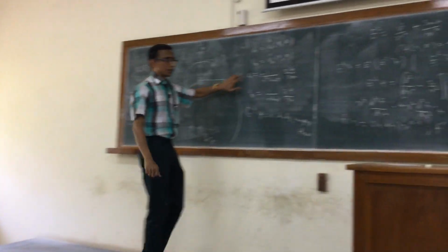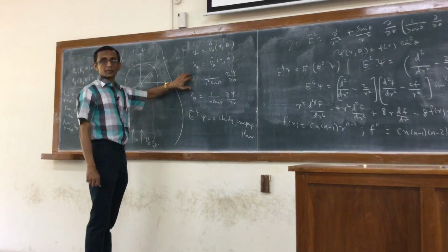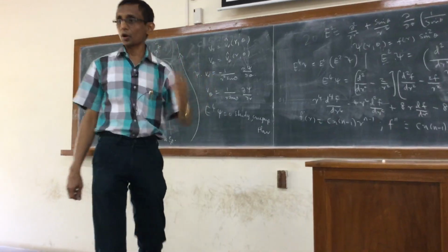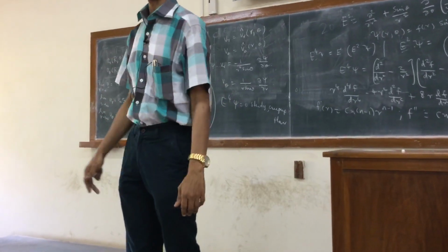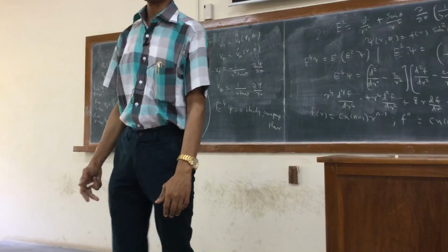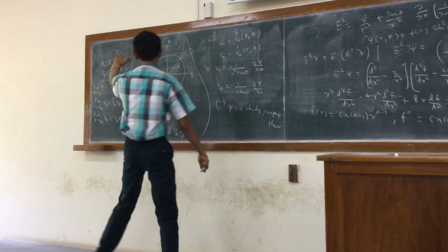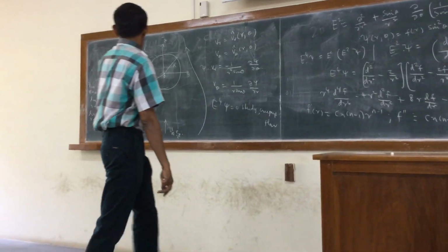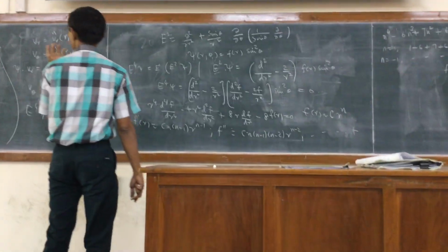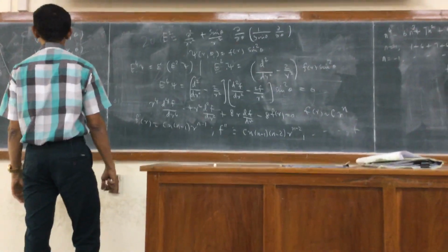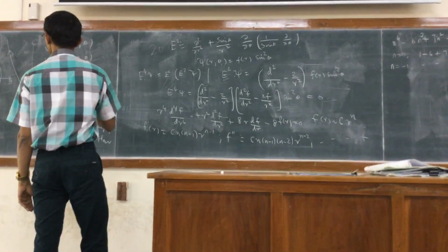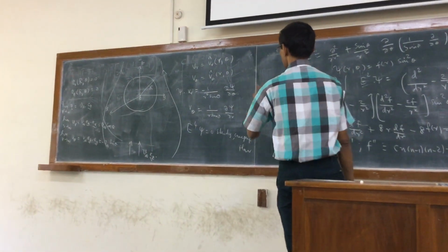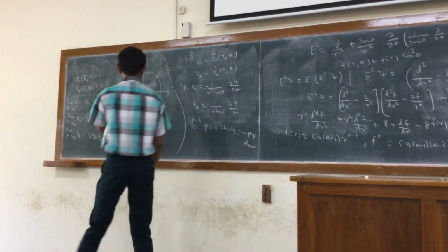You can use these equations to express Vr and V theta. They would have the four undetermined constants, and then you apply those boundary conditions. That's one way of doing it. Another way is to convert these to boundary conditions on psi. You do one or the other. Making Vr of R, theta equal to 0, and V theta of R, theta equal to 0 is very easy to write. Let me write those boundary conditions here.